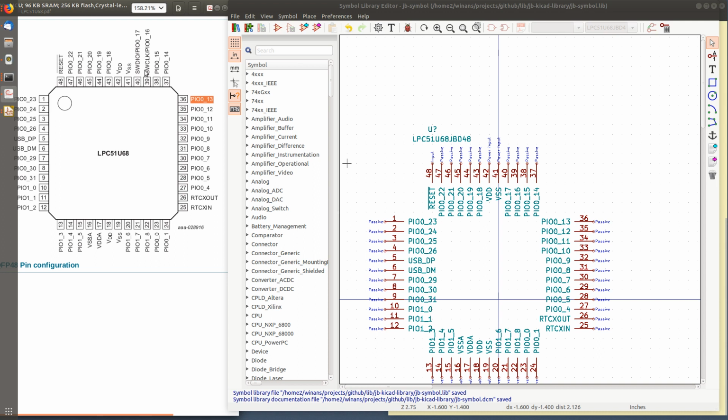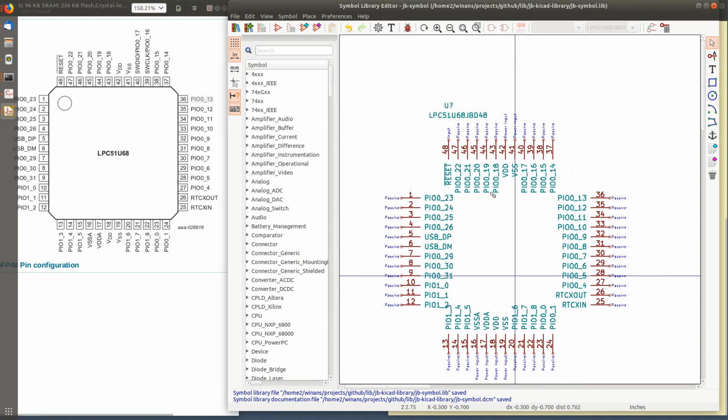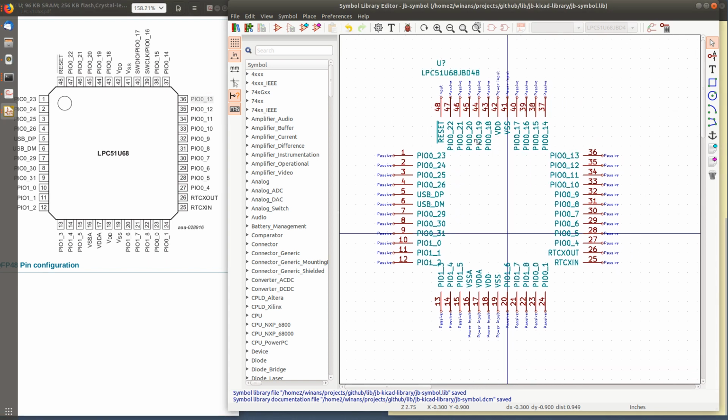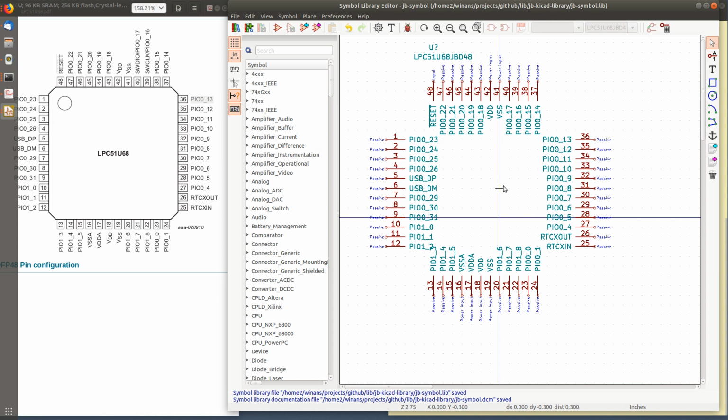This is the debugging I/O system. I don't care. I don't actually use it on this chip anyway because it has a USB programmer built into itself. So I'm looking at PIO 0, 18 to 21, 22, and reset on 40. I can't believe I did all these right on the first try. That just means I haven't figured out what's wrong with it yet. So beware.